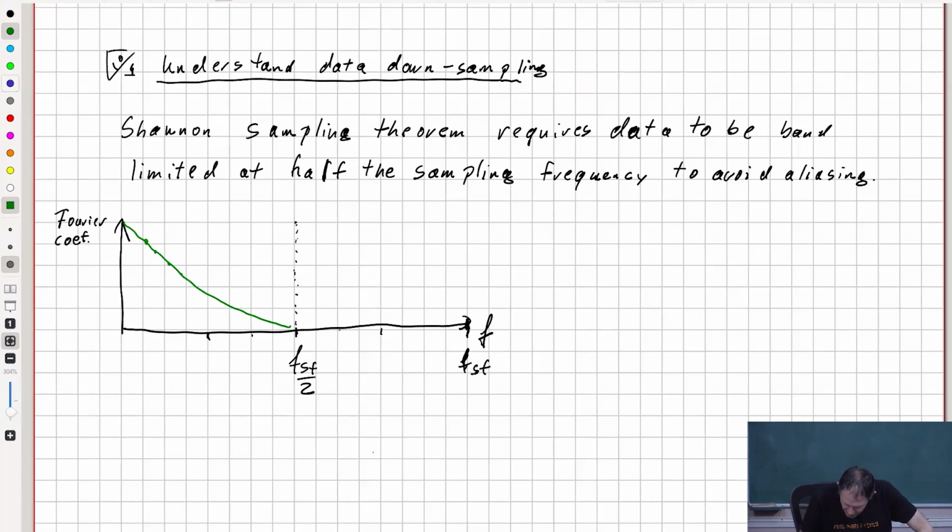You get something that's called a mirror image, mirror data. So simply, the spectrum of your signal is mirrored around this half frequency. Yeah. So that's fine as long as this thing goes down here to 0 quickly enough.